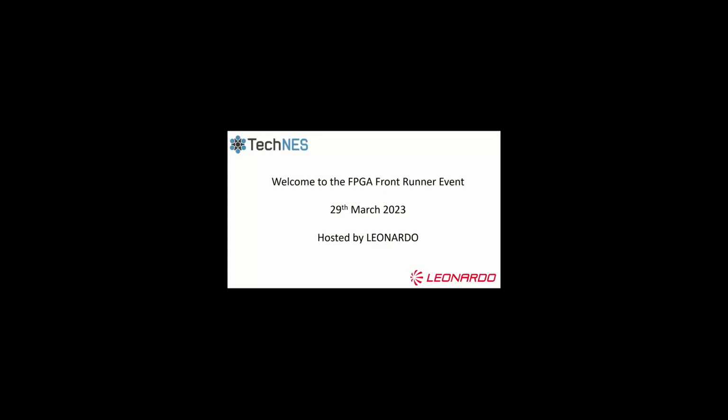There's a lot going on in this, but I'll try and walk through it. That orange block on the right-hand side is a block diagram of what we're trying to aim for: some sort of generated IP core running on an FPGA. It's normally got some accessible registers for control states, feeding data in, that sort of thing. And MATLAB can instantiate that in an FPGA build with an AXI bus master that can run over JTAG, for example, and control it straight from there. So you can run it live in the same sort of environment as you can for the rest of the models.